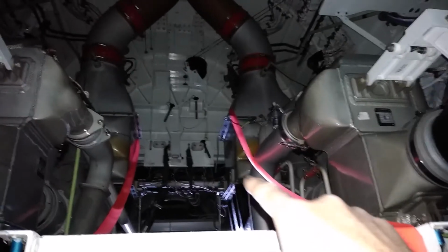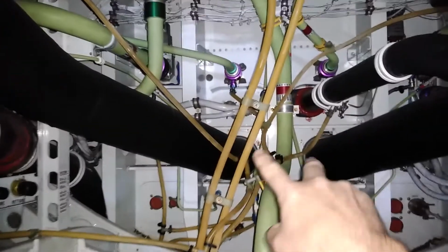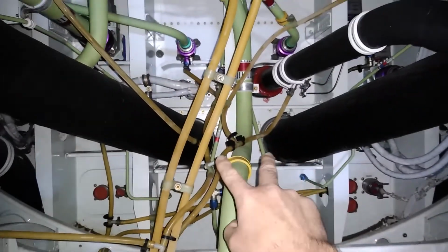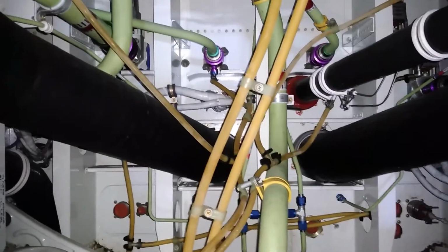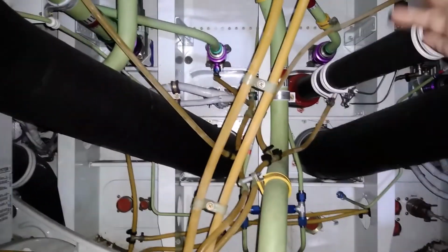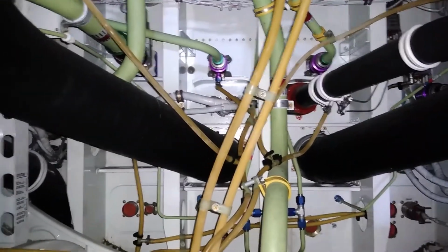Again, it goes from here, from the engines or the APUs, through the cooling packs, air conditioning packs, through these ducts, through the pressure bulkhead. This is where the check valves are. Forward of that, you have the mix manifold, and then it goes distributed and recirculated through the cabin, etc., until